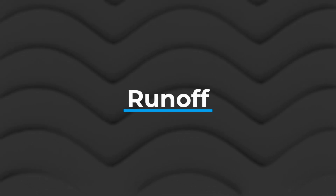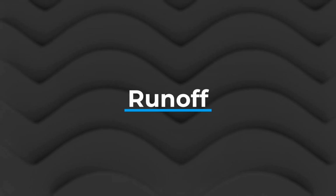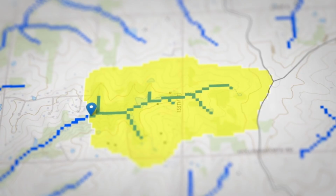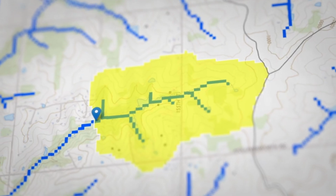Whenever it comes to most ponds and lakes, we're really worried about the runoff feeding them. Obviously, we need to make sure it stays full. We need to make sure it's getting enough water to feed it. So one big piece of the design aspect, whether it's a repair or a construction, is taking into account the local rainfall and the weather history for that specific geological location.